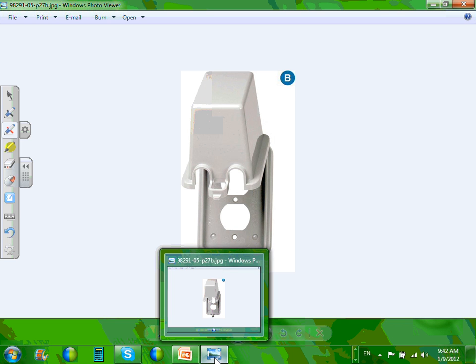I'm saying you can plug it into a 20 amp receptacle that's on a 20 amp breaker. If it consumes 20 amps, you're over your 80%. The 20 amp and 15 amp are kind of weird because they allow you to plug a 15 amp load in a 20 amp receptacle, but not the other way around. They don't allow you to plug a 20 amp load in a 15 amp receptacle.